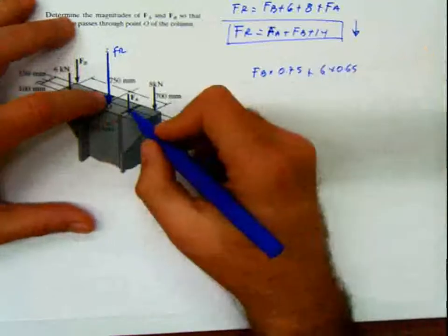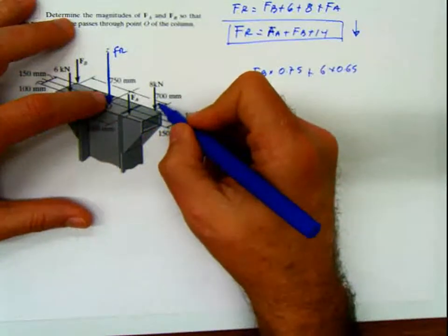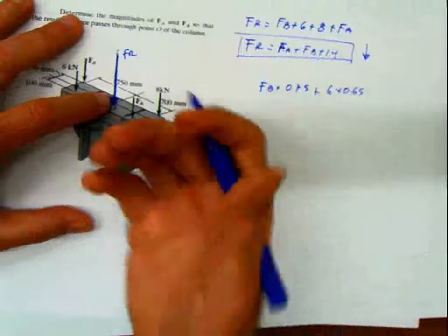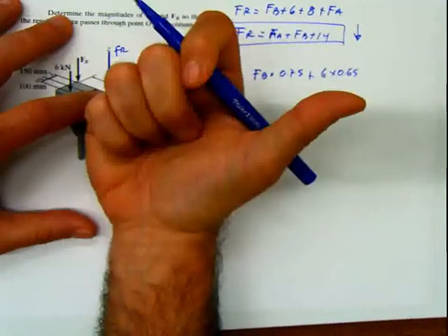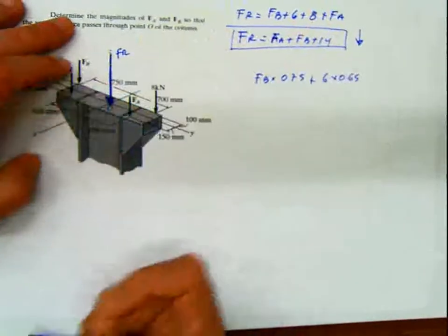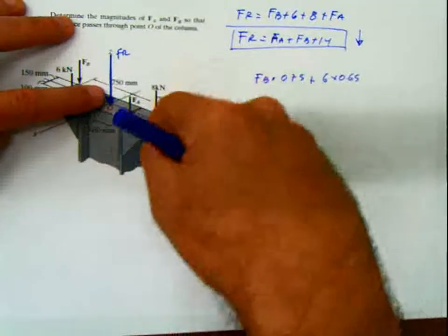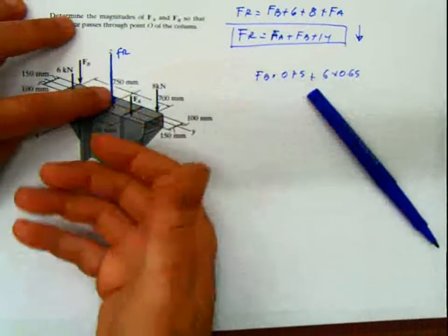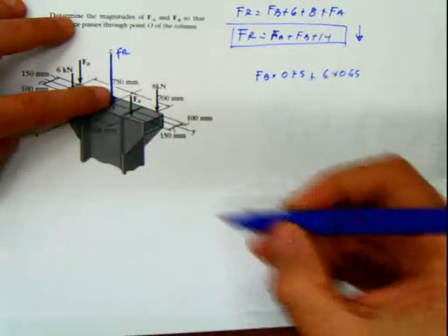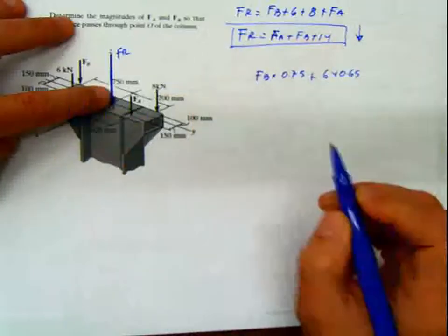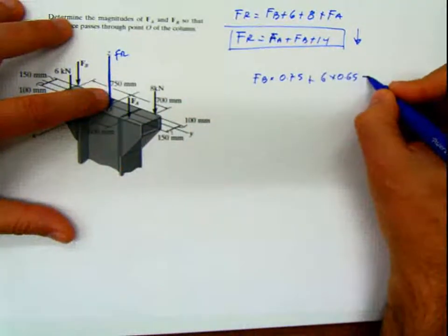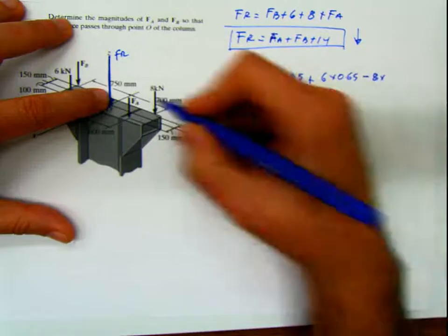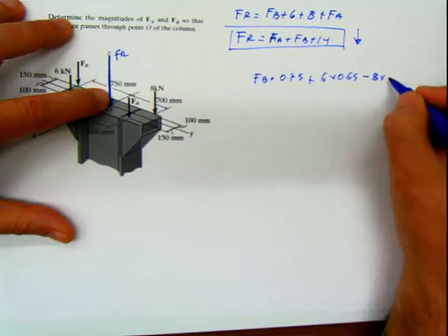Now, what about this one? If I apply this force of 8 in this direction, the rotational movement about the x-axis is going to go in. Do you see that? Apply the force, keep the pin here, and now imagine how it's movement. It's movement entering into the axis. So that's going to be negative 8 times this distance. This distance is 0.7.